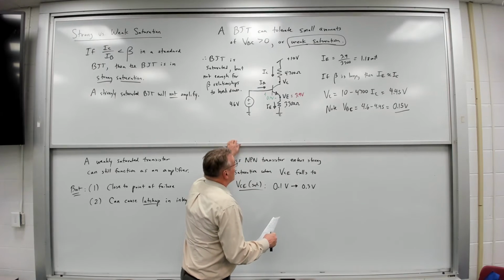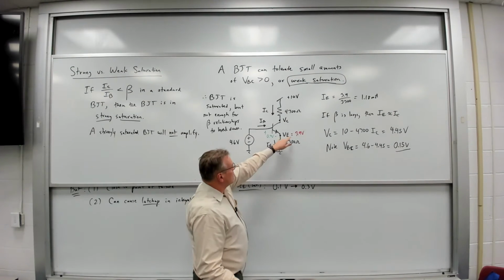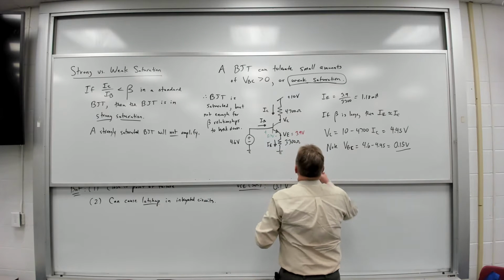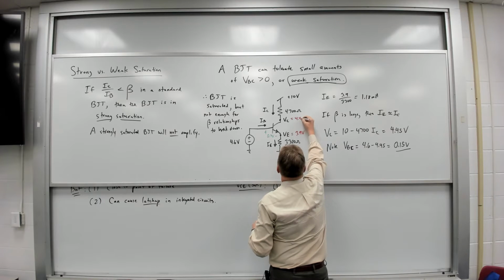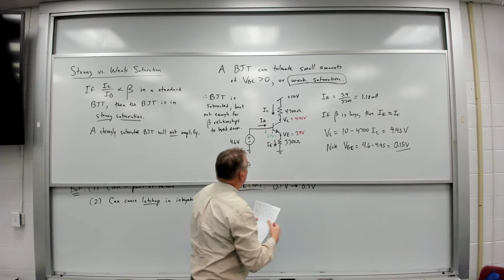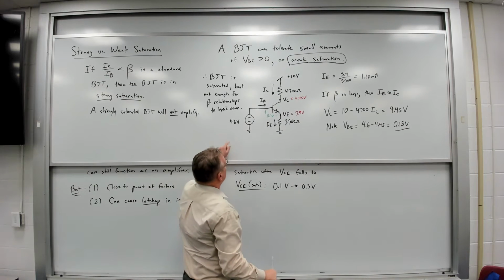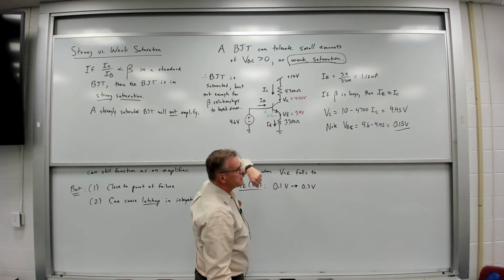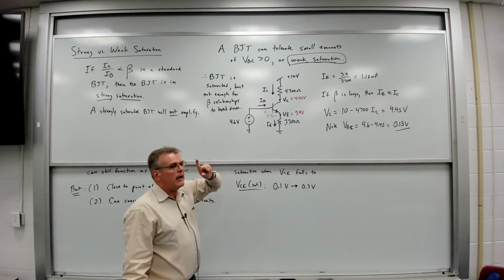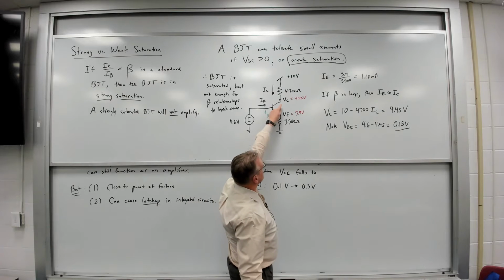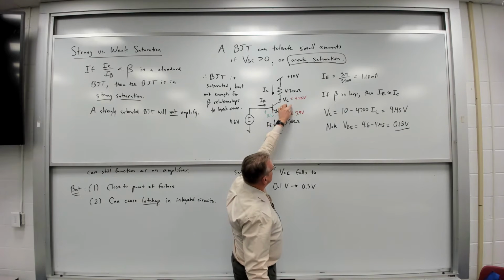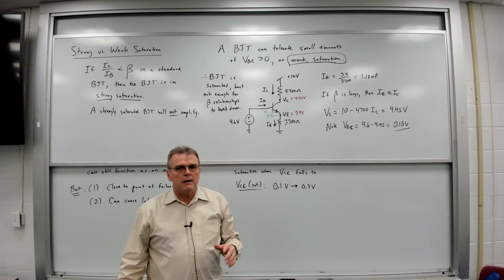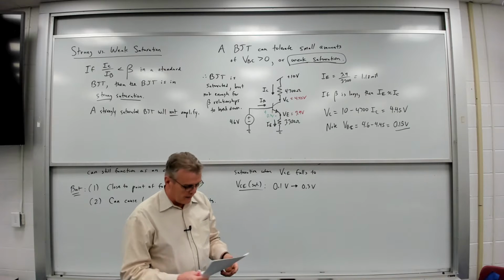So think about what's happening here with this design. For this circuit, I've got 3.9 volts. VC is equal to 4.45 volts. And if I keep increasing the current flowing through IC, if I keep increasing the IC current and the IE current, then what I'm going to find is the value of VC drops until finally VCE is going to hit, like I said, somewhere between 0.1 to 0.3 volts. And at that point, the beta relationships are going to break down entirely.